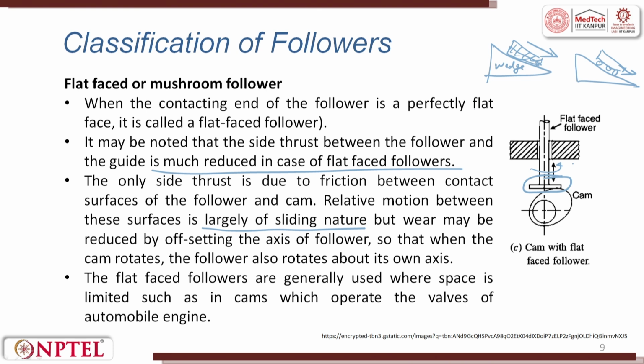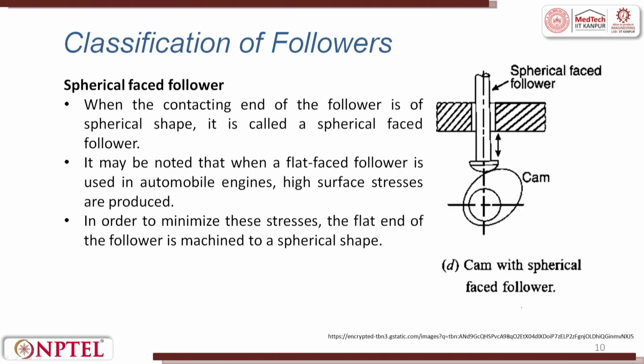Flat faced followers are generally used where space is limited, such as cams which operate the valves of an automobile engine. Then you can have a spherical faced follower. Spherical is a combination of roller and flat.